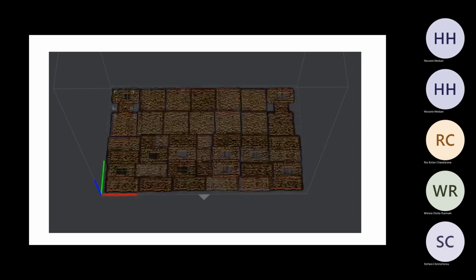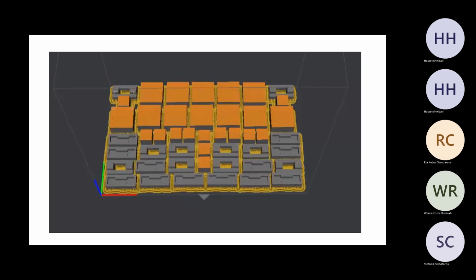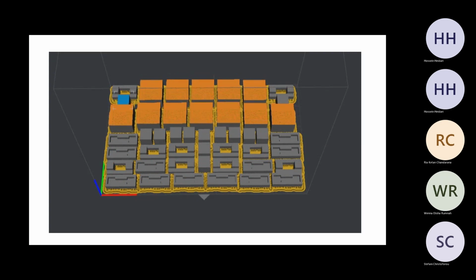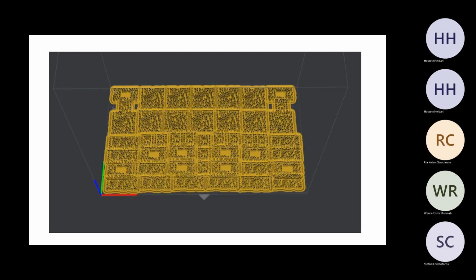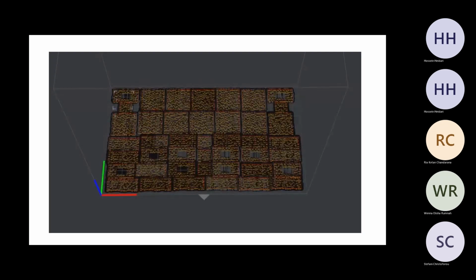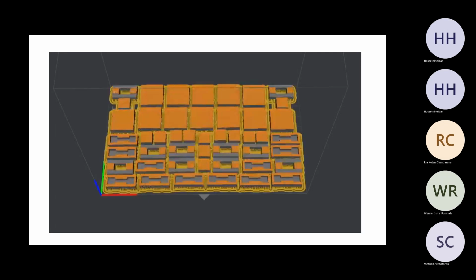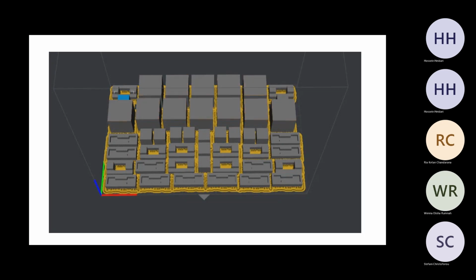So you actually design the absorber so that it only goes as far as 100 microns, which is that layer of interest, and doesn't go beyond that. It basically drops off significantly. That means that in that cure box, your light coming as a flood exposure source from everywhere is also just going to go deep in for about, let's say if you give it 6 minutes, even if the region is a bit more inside with lower intensity, it's still going to have more time to cure, but maximum it's going to go about 0.5 millimeter, 1 millimeter inside. That's another inherent challenge of this process.